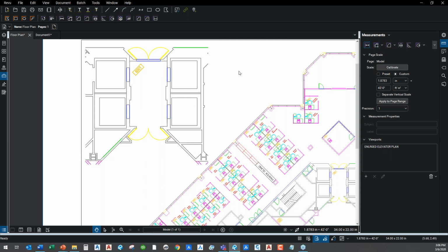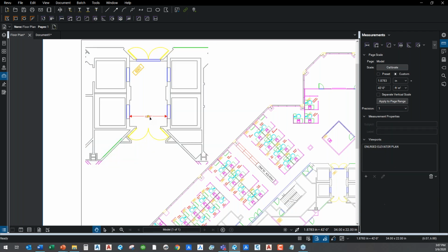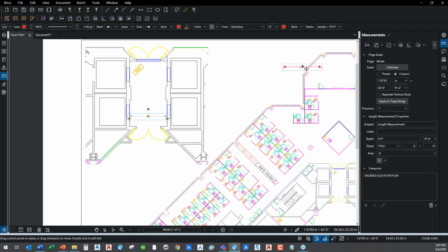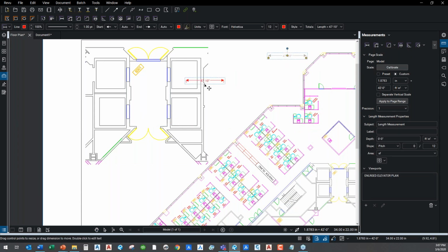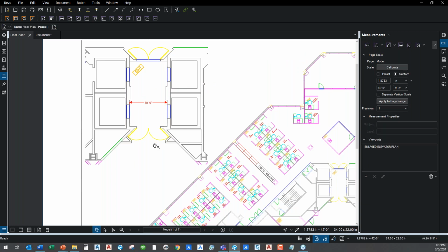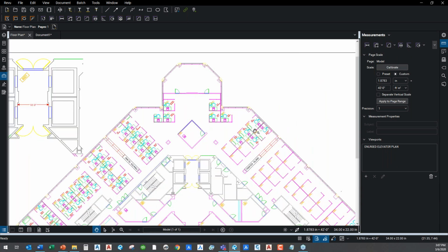Right? Even though the rest of the drawing is at a different scale, I'll just throw that dimension back on there to show you. Okay, that if I go in and move that dimension outside of that box, see that's actually 47 feet at the overall scale we were. So I've taken it almost 4 times, and you see when I go back, it puts it right back to 10 feet. Okay, so it's a very easy way to do that, and you can do that with as many different plans or as many different areas as you need within your document. Right? I can just easily go back in and do the whole thing again.